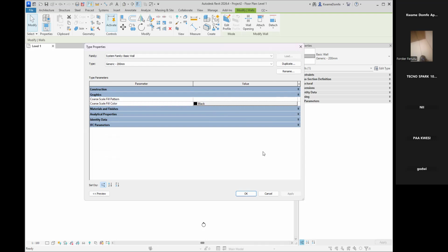That is where you create a 3D model, you add a room. When you add a room to it, you can annotate the room in plan, in section, in everywhere, in reflected ceiling plan. But if you don't add the room, then it means that you'll be compelled to use text to label your rooms. And using text to label your rooms doesn't make sense in Revit. And I know some people who use Revit and still use text to label their rooms.